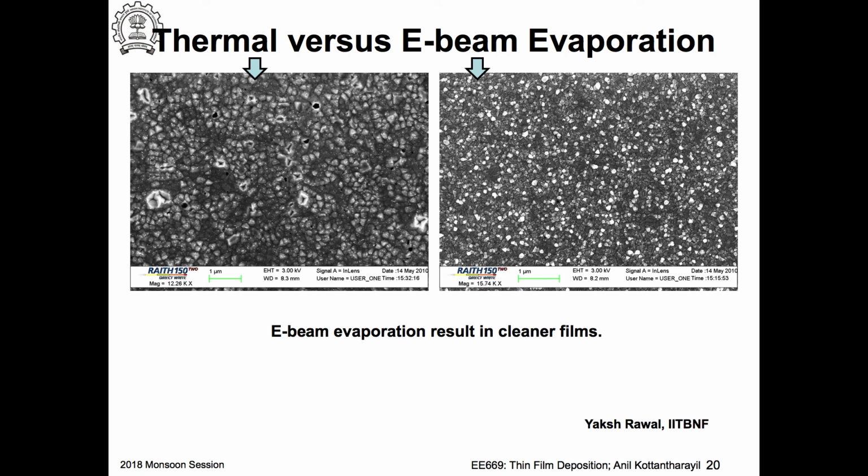of the films, and you find in this case a little bit of carbon coming from the graphite. Yeah? So unless you pay a lot of money to get very good quality graphite, you can get a lot of carbon in the film. So as a consequence, the thermally evaporated aluminum would typically have higher resistance. Yeah. So for many applications, it is not acceptable.